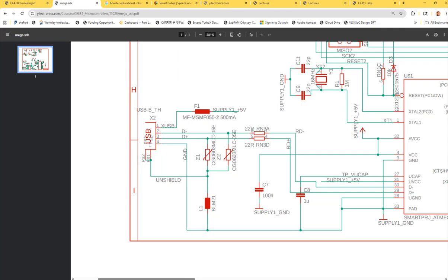One more thing, I'll probably repeat it on Monday. When you start a schematic, you keep drawing, keep placing parts in the schematic. If you don't click that schematic to board button, you won't have a board window. You can work on the schematic, save it, close it, doesn't matter.